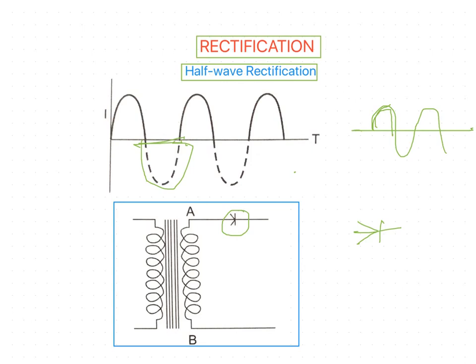Alternating current is bidirectional. So here, during alternate half cycles, the alternating current is blocked. Here the continuous line represents the current flow, and the dotted lines, which are the reverse waves, represent no flow of current. The resulting current that is obtained is unidirectional, only one directional current like this.